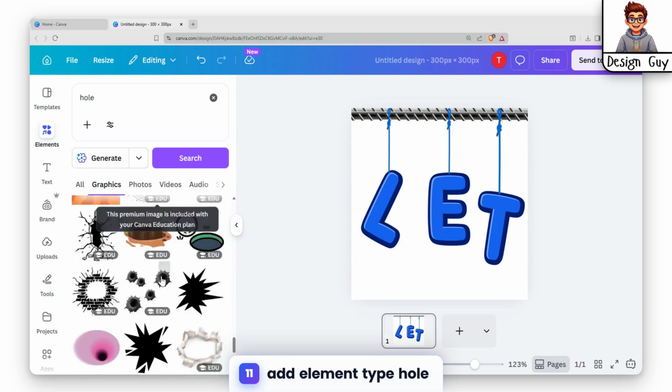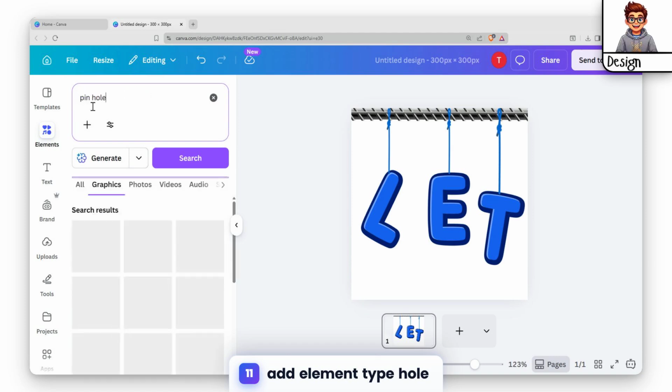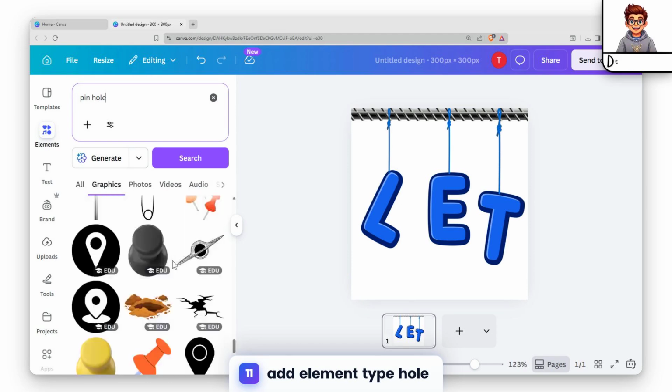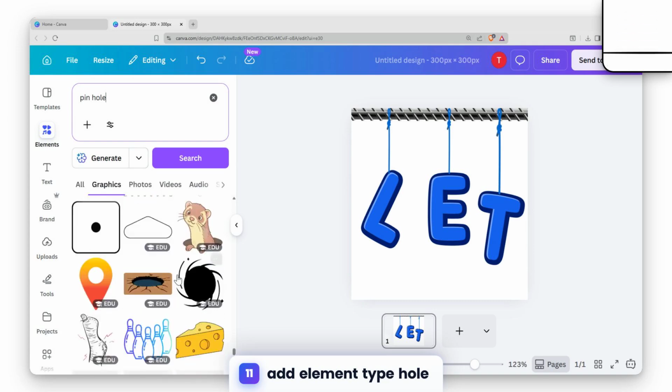Next, align the circle with your main design. Use the alignment options to center the circle horizontally and vertically relative to the part. This ensures the rope hole is placed accurately. Once the circle is placed and aligned, check its position to confirm it meets your design specifications. Now, subtract or cut the circle from your base object to form the actual hole.